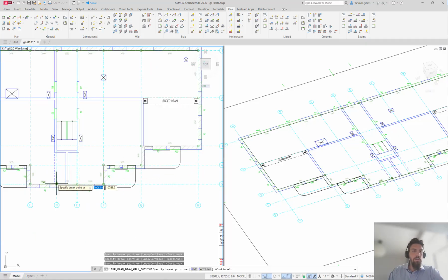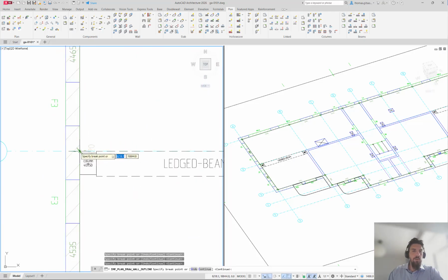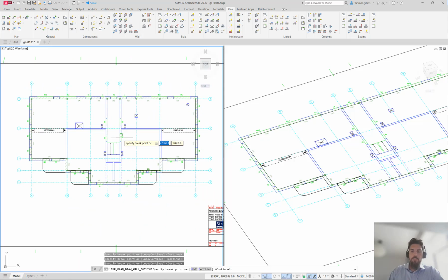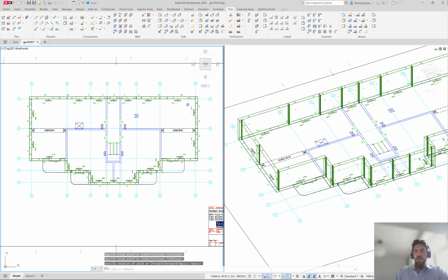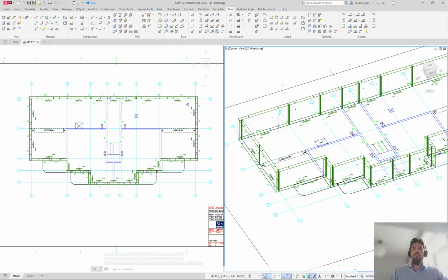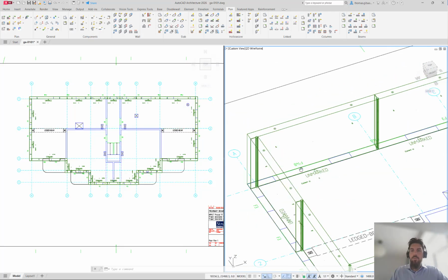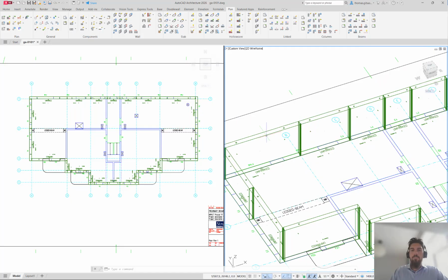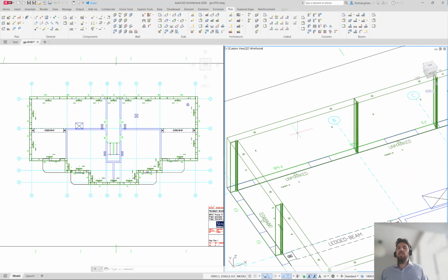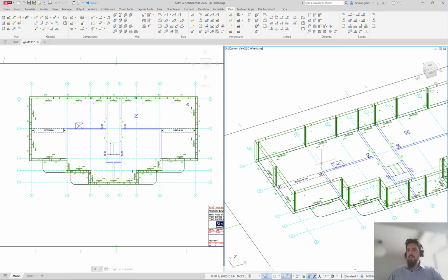Again, now we're being cautious. We don't want to create any issues. And then we say enter and say apply. If you focus on the right side of your screen, you will be able to see that the walls are being created in full 3D. What do the walls include right now? The walls include automatic lifters, edge details, connections between the different walls, and bracings. These are the main things that we can create automatically when we apply a definition in Impact.